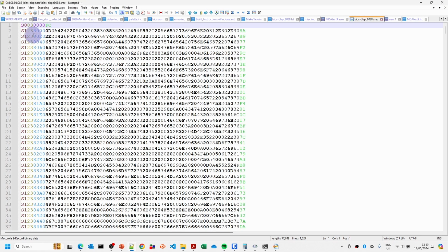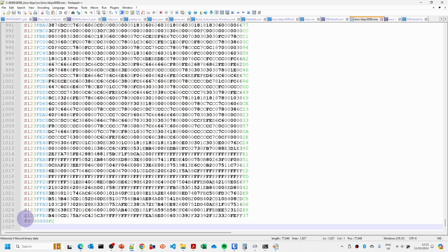Then if we have a look at the srecord file, you can see here that the srecord file is just going to be loading this. The srecord only does a 64K file here in our definition. So when we're going to set the extra segment to be 6000, that effectively means that this will be loading from 68000. We'll go all the way down to the bottom to 6FFFE0. This here is our reset vector, effectively.